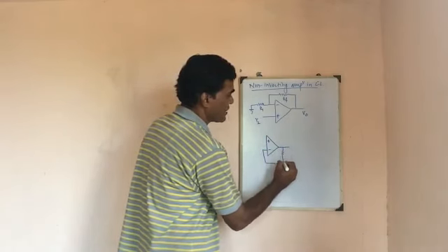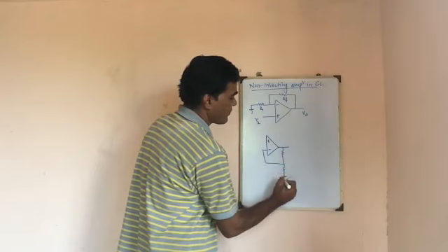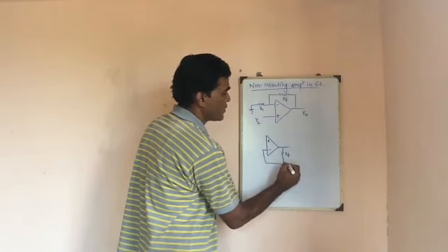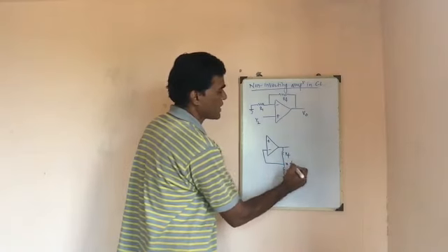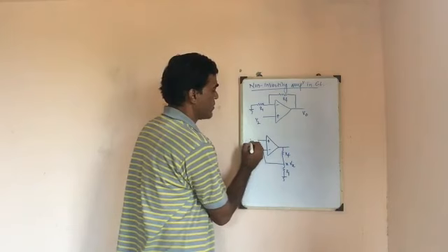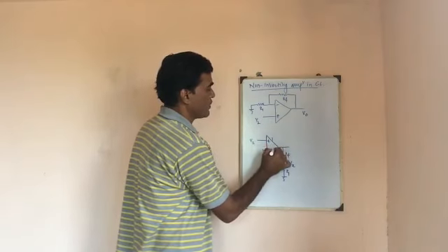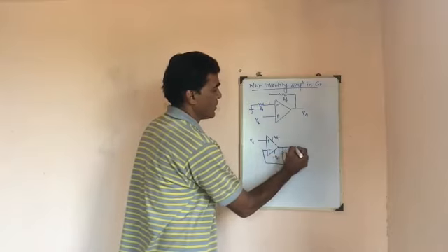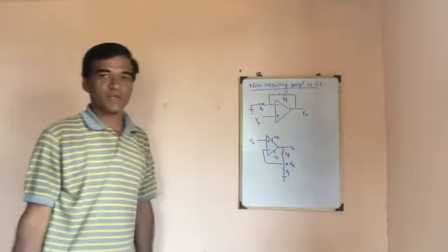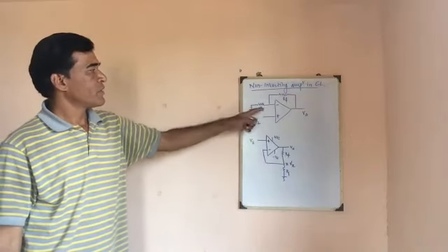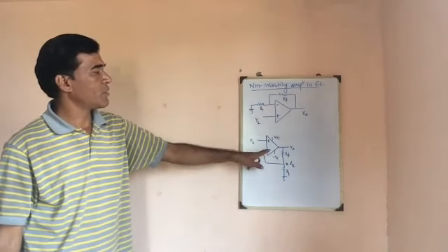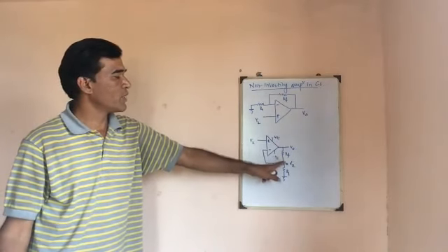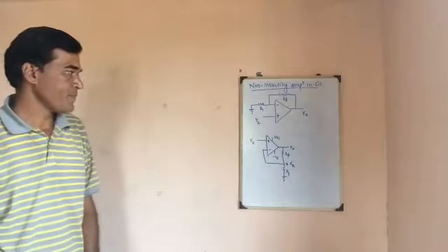Here we have the feedback resistor Rf, this is R1, this is Rf, this is the node X, and the voltage at this node X is Vx, and the input is applied to the non-inverting terminal. So these are the supply voltages and the output voltage. Is it right? The circuit is set. So at the negative terminal, R1 is grounded, and Rf is in between the output voltage and node X.